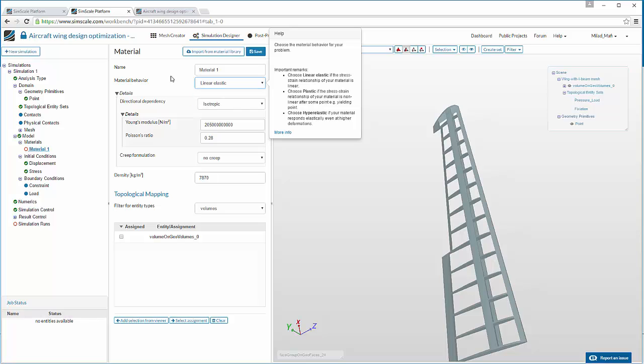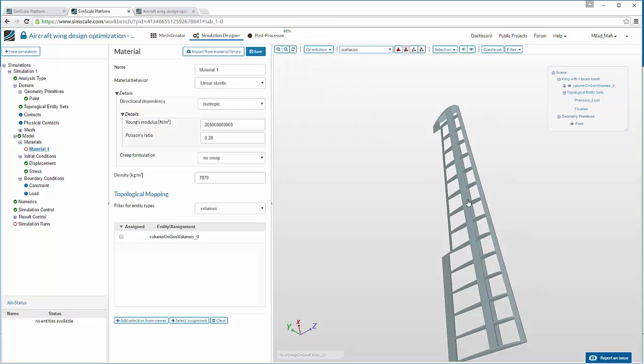So we will use linear elastic since we will use aluminium for the frame, a special aluminium. And we have also a library which contains a lot of materials. It's a ready-to-use model, but unfortunately our material, which is called aluminium 2024, a standard material in the aerospace industry, is not part of this library, so we have to define everything manually.